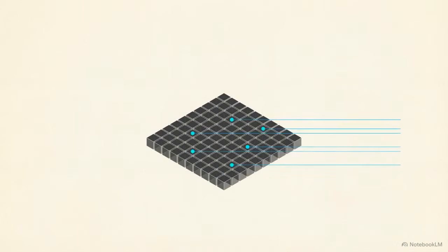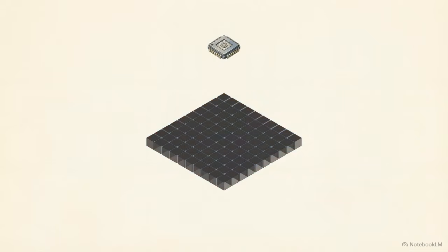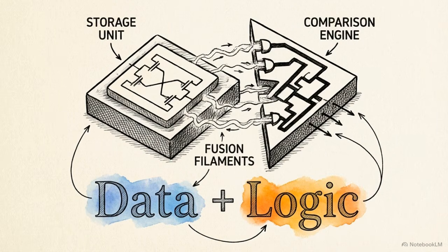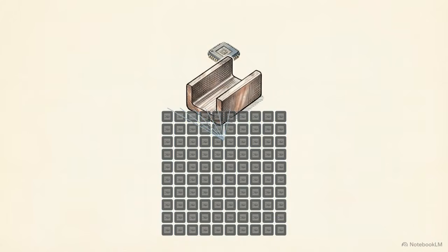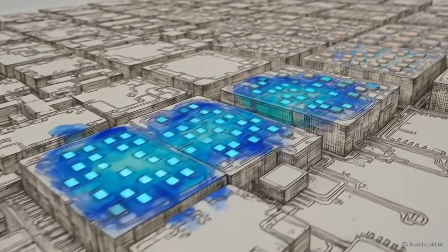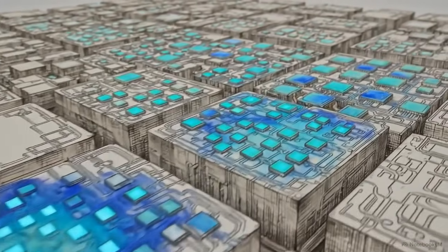Multi-port topologies solve the problem of moving data out of the array, but the challenge of network routing requires finding data entirely in place. This requires content addressable memory, or CAM. It operates in exact reverse to standard SRAM. The architectural formula that makes CAM possible is explicit. The hardware requires both storage and an embedded comparison circuit. The controller broadcasts a single search word to all memory cells simultaneously. The array evaluates the input and instantly outputs the exact address location of the match. By embedding comparison logic directly inside the storage array, CAM effectively operates as a massive parallel computational engine.